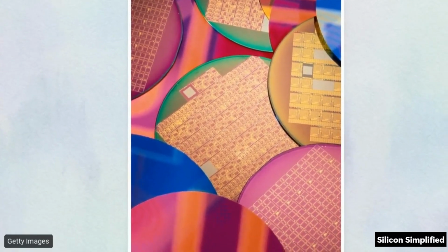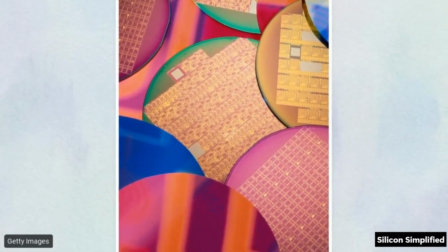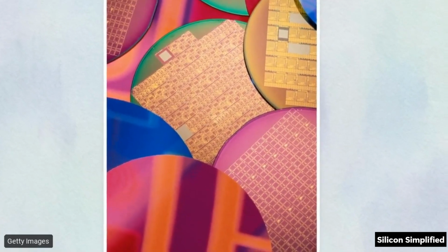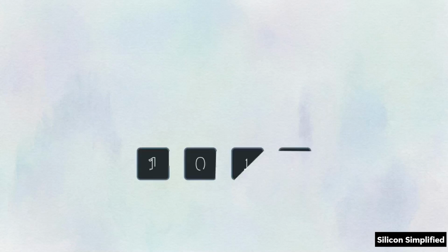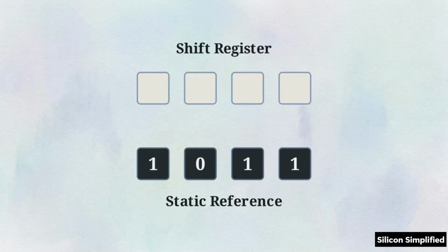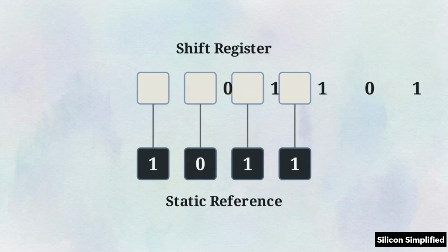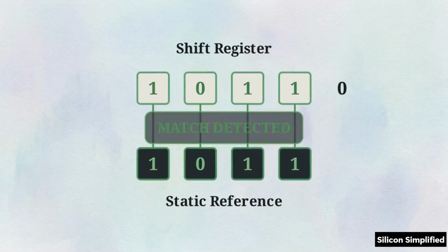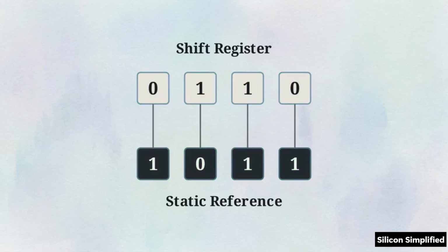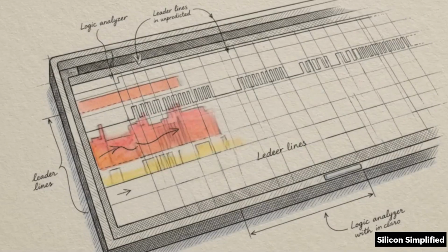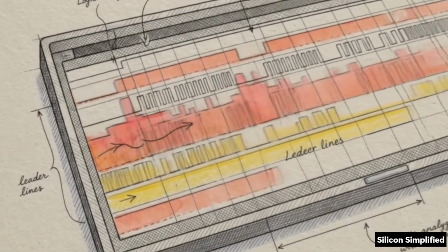Hardware engineering ultimately comes down to a physical medium. We're etching logic into literal silicon wafers, which means every algorithm we design has hard physical constraints. Take a standard sequence detector. Traditionally, engineers build these using a fixed pattern shift register. The hardware stores the last few incoming bits and checks against a hard-coded string, looking to detect exactly 1011 or another static pattern. But the real world does not always deliver neat, fixed strings.